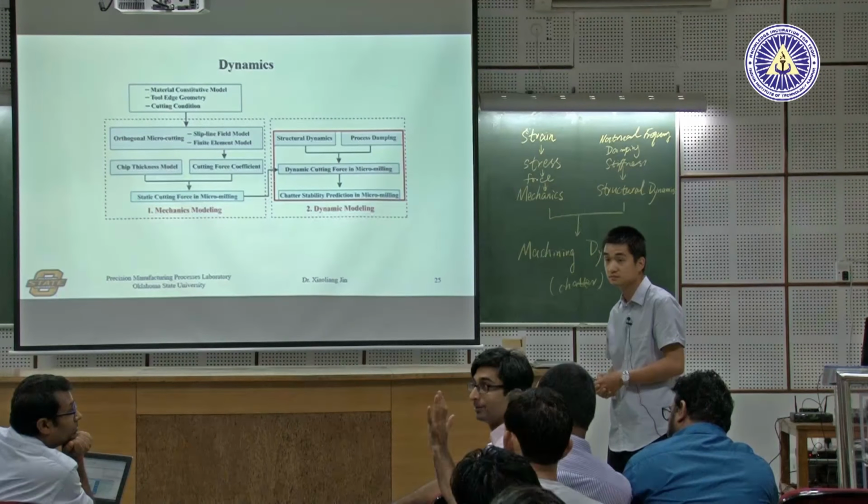So I think the basic idea is, whether you want to take data in AC or DC, because in DC there will always be a drift. So one way to do it would be to take AC data, so drifts will die out, but then you lose your mean. So there are ways and means to do it.